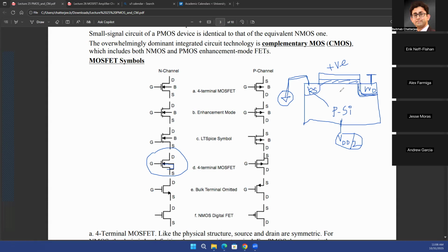It creates an additional current flow and additional power consumption, the MOSFET will start heating up, and all of these things are unintentional. You never wanted that. You're not achieving anything by having this p-type silicon connected to a positive voltage.